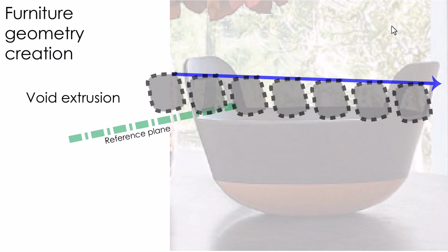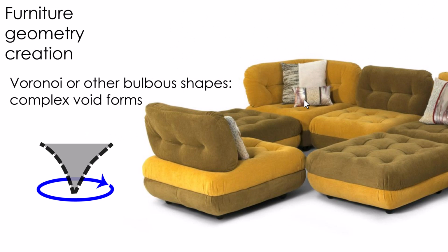You'd actually have to create a reference plane to draw a void extrusion that will eat away the handles, and I guess you'd have to make another one to eat away the rest of the model. And these do get complicated because now you're drawing reference planes on the ground that you can then use to draw these profiles.